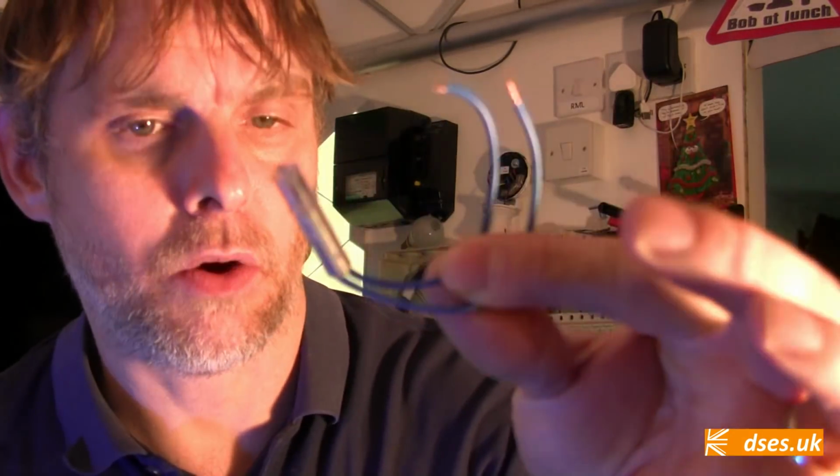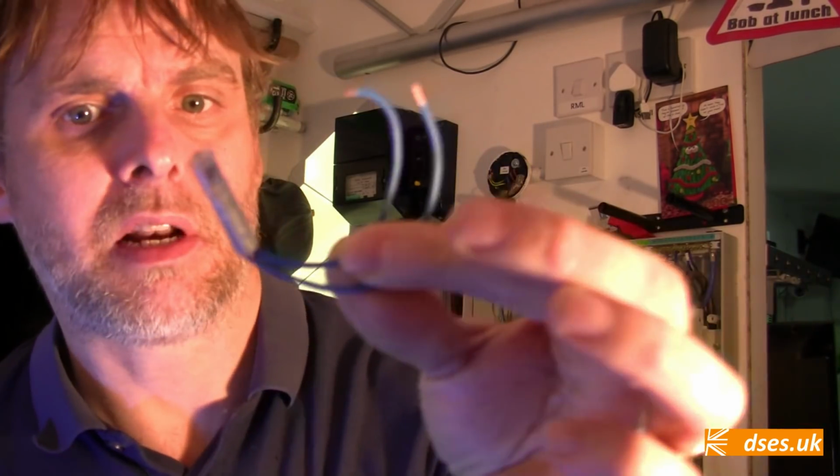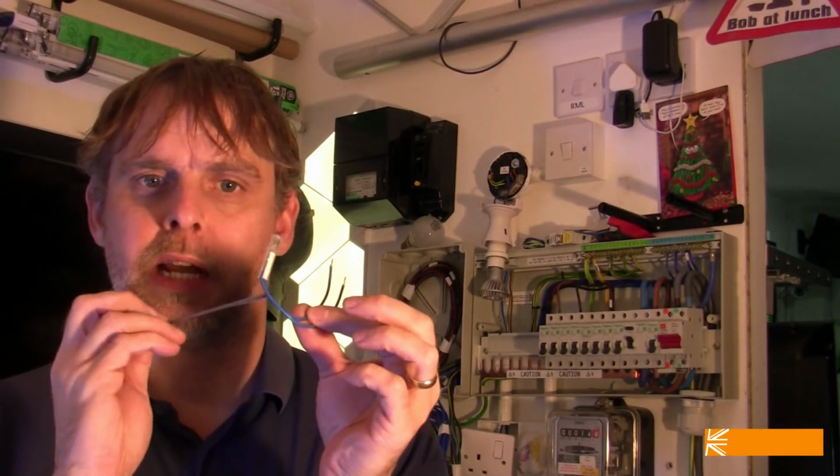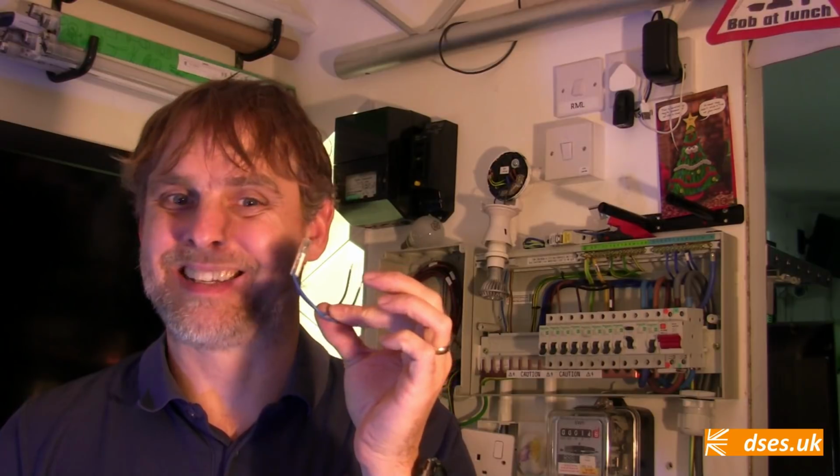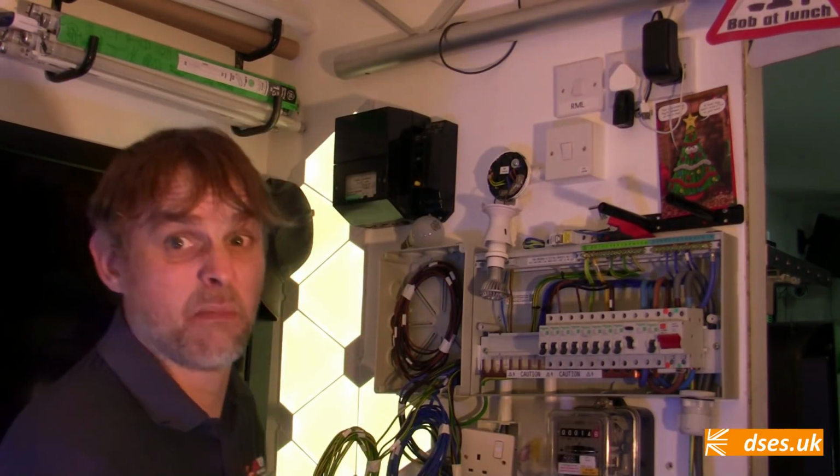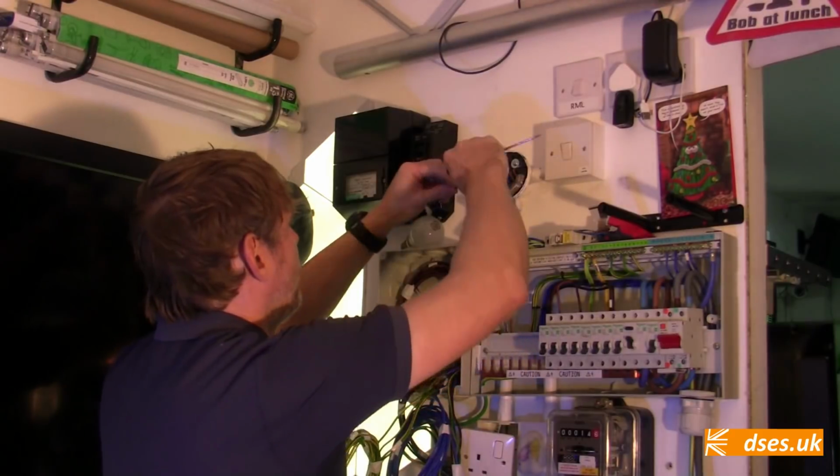This is a neon indicator. I have an Amazon link to such in the description, although this particular one has been removed from a defunct electric shower. If I connect this between line and neutral, then the resistance of this indicator causes the lamp to extinguish and the indicator to faintly glow instead, as it sucks up the waste current. This indicator is small enough that it can be lost above the ceiling or behind the light fitting. When power is restored to the light circuit, then the indicator glows brighter, but if it's positioned in such a way that you can't see it, then it doesn't really matter, does it? So let's put that on.